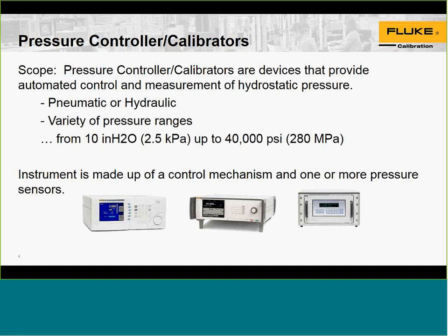The controller on the right is hydraulic only, a PCH, formerly DH Instruments pressure controller, which uses a reference pressure transducer or a utility silicon-based sensor. The maximum range you can get on this controller is about 30,000 psi, hydraulic only.